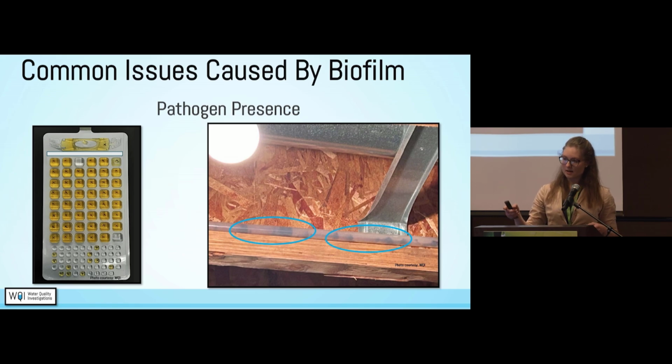So this tray is actually a way that we are able to statistically count how many bacteria are in that sample that are coliforms and also E. coli. Now, if we get a sample in that has a count of 1, we might suspect it's a sampling error, or it could be an overabundance of total bacteria, and that causes false positives at times. But when we have a sample that looks like this, we definitely know there's a problem.